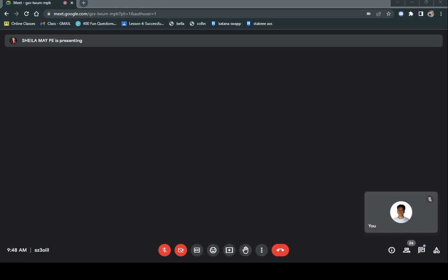ID is IDSS times 1 minus VGS over VP, squared. And we have IDSS at 10 times 10 to the negative 3, that's milli. 1 minus VGS. We don't have VGS yet. VP is negative 3.5, squared.